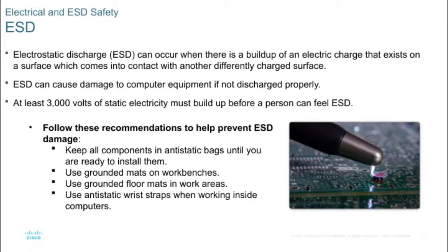Electrostatic discharge, or ESD, can sneak up on us when a buildup of static electricity jumps between surfaces. It's invisible, but it can seriously damage computer components if we're not careful. To keep things safe, we follow some simple steps. We keep parts in anti-static bags until installation. We work on grounded mats, both on benches and floors. And we wear anti-static wrist straps when handling sensitive hardware inside computers. These precautions help us avoid costly damage and keep everything running smoothly.